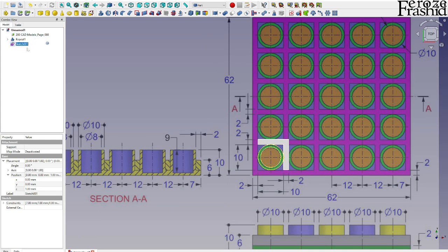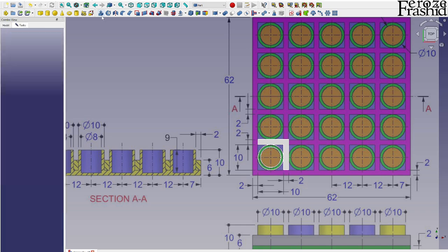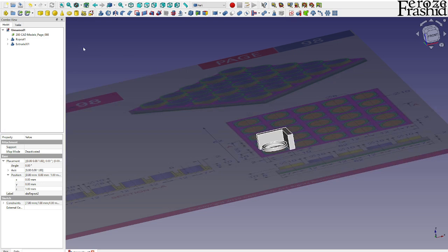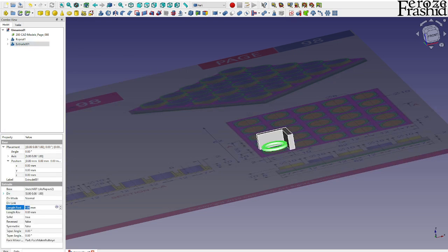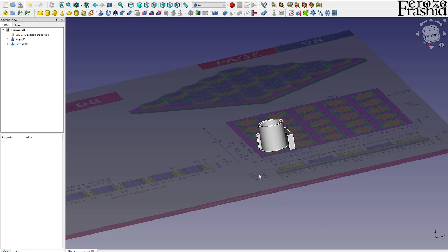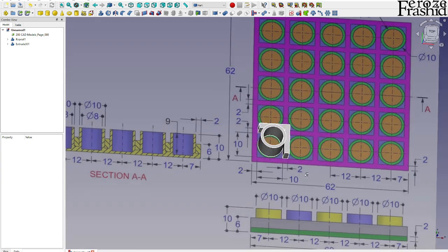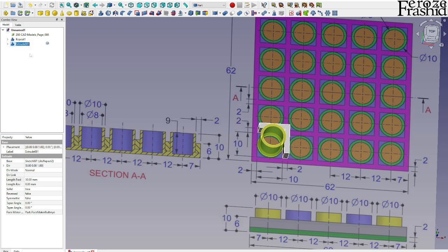So that part, again, sketch repeat 2. And that will go up by 10 millimeter. And at the bottom, there will be 1 millimeter pad. We will take care of that later. So now we have these two. So this is repeat 2. And I want to make that one object with unionizing it.